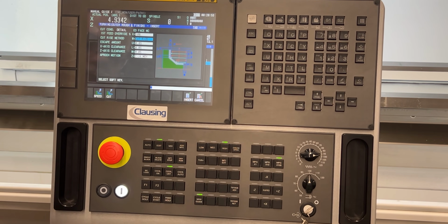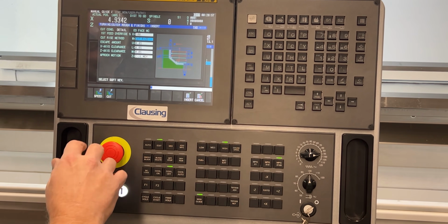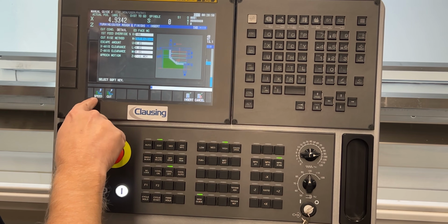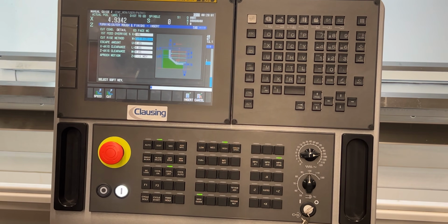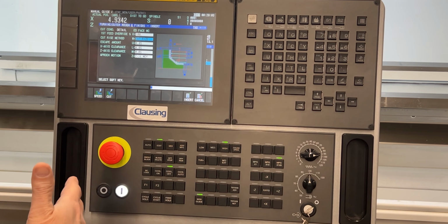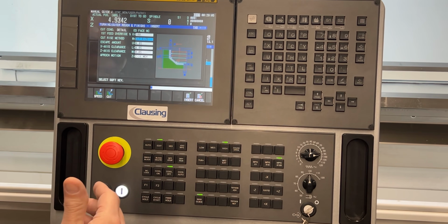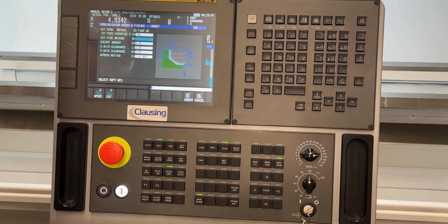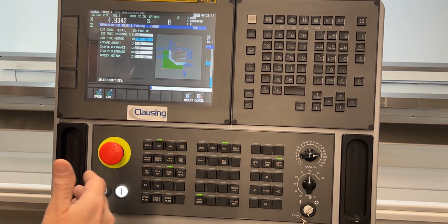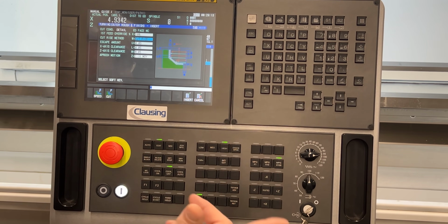Then I have a choice between speed cut and cut rise. So the speed cut down here would be that at the end of the pass, they'll come off on a 45 degree, shoot back to the front, go into the next depth of cut, and come back down, come off at a 45 degree, shoot back to the front.